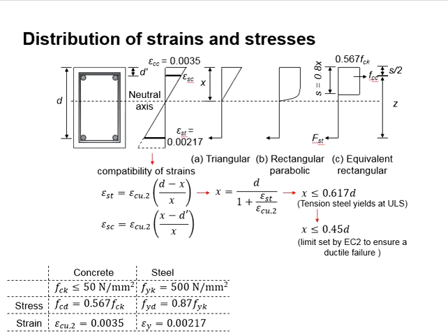You know that in the reinforced concrete beam section, there is a neutral axis, which is located at the distance x from the top of the beam. This neutral axis divides the compressive regions and tension regions. The concrete has the capacity to undergo compression, while the steel is designed to take the tensile stress within the section. Now, this x here varies in accordance to the load applied onto the reinforced concrete beam.